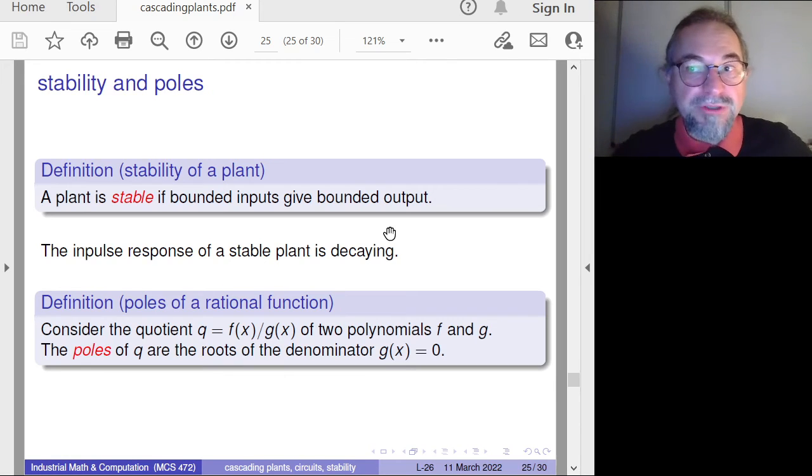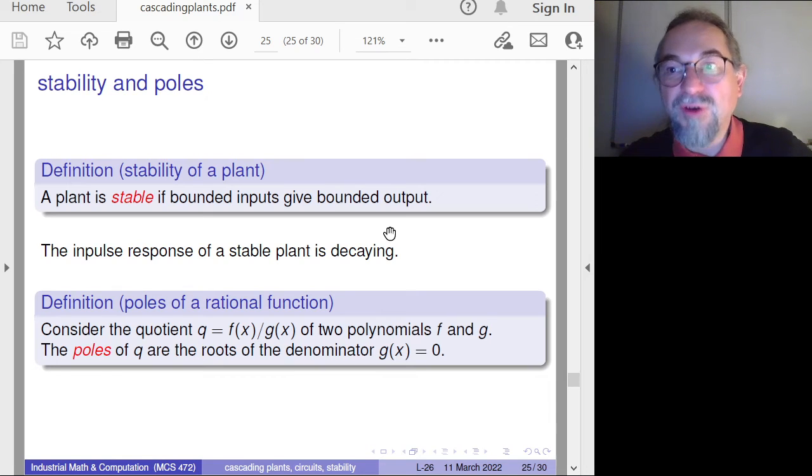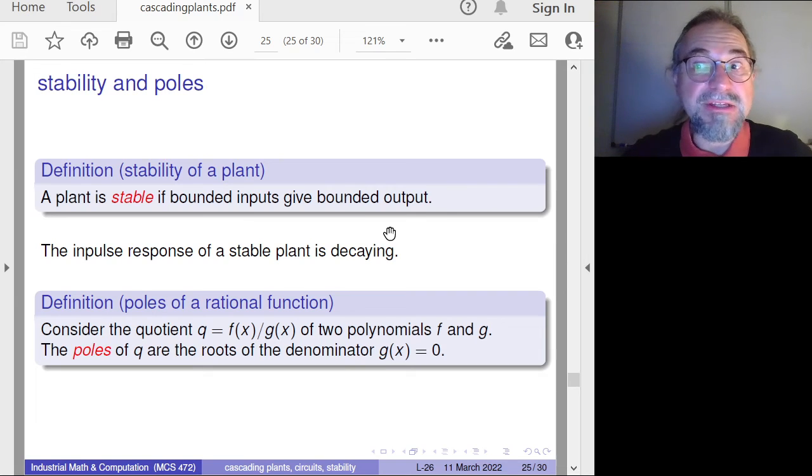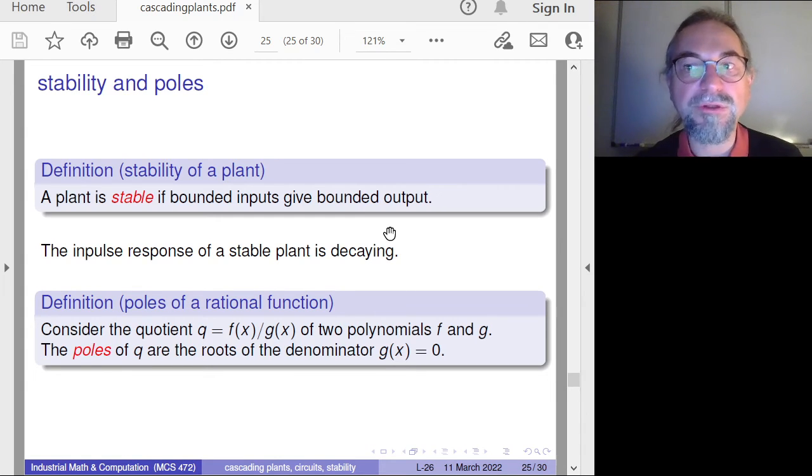So the poles are where essentially the transfer function is not defined as an algebraic expression, so there is an asymptote there. So this is where things are getting interesting. This is what characterizes the plant. That's an interesting perspective. Where the transfer function is not defined algebraically, or in classical number sense, because you have an asymptote, this is where we actually are going to characterize the behavior of the plant.